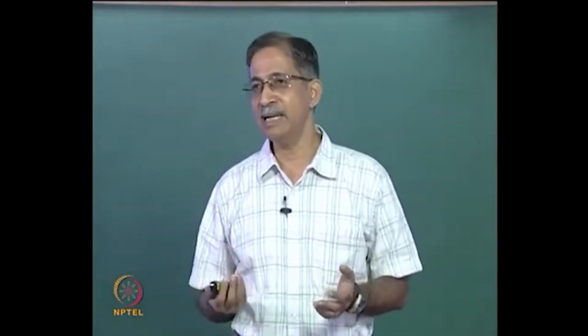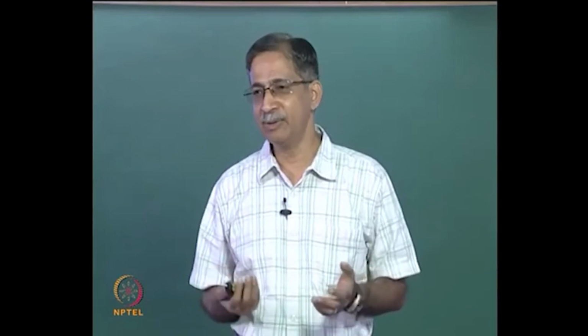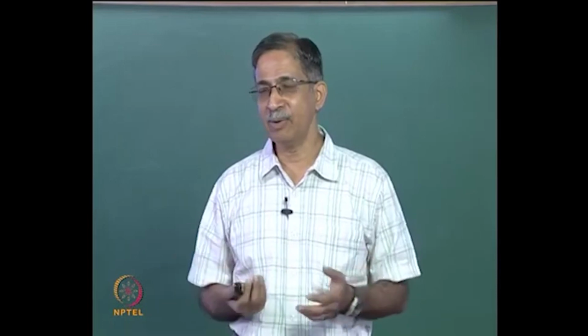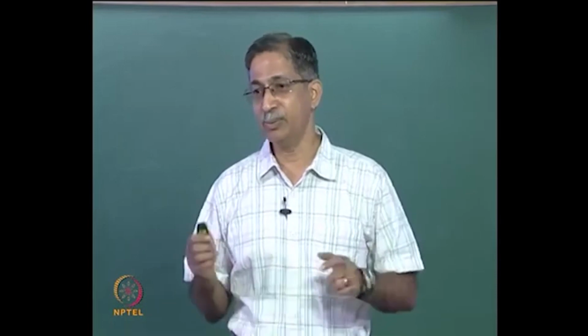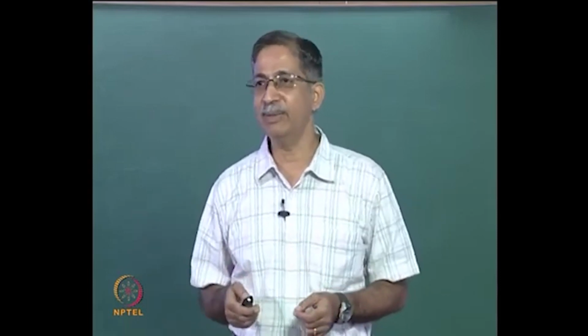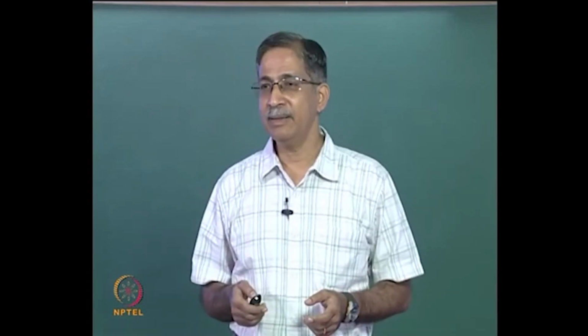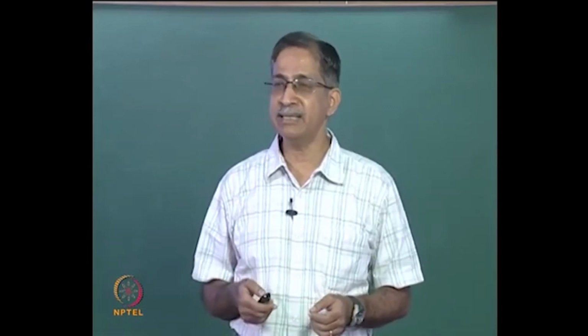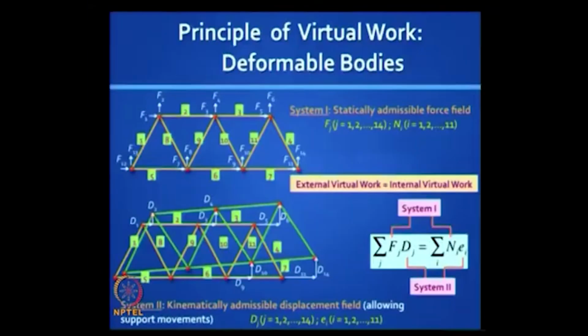There is some commonality between those numbers, but there is no cause effect relationship, and the sequence of loading and all do not come into this, which would come in an energy formulation. So that is the advantage of a virtual work formulation. Now if you take the internal field, the internal forces Ni in system 1 and corresponding Ei in system 2, and do a product and an algebraic sum, then you have the internal virtual work.